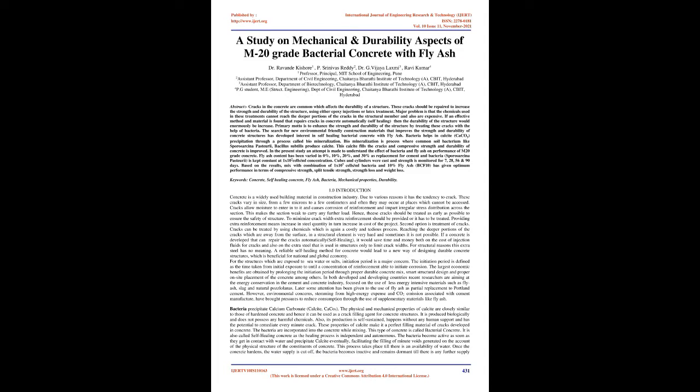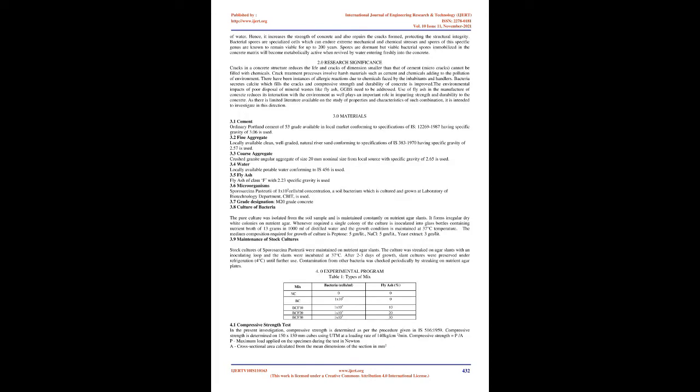Based on the results, the mix with a combination of 1x10^7 cells/ml bacteria and 10% fly ash, BCF10, has given optimum performance in terms of compressive strength, split tensile strength, strength loss, and weight loss. Keywords: concrete, self-healing concrete, fly ash, bacteria, mechanical properties, durability.